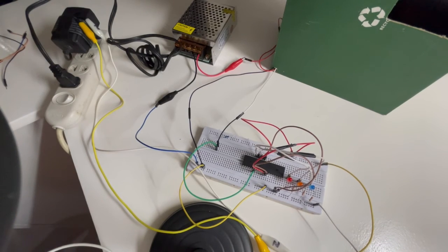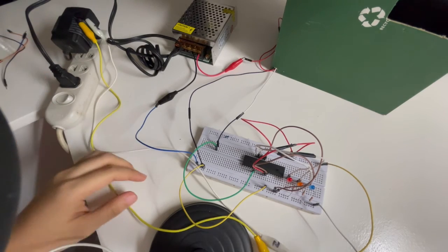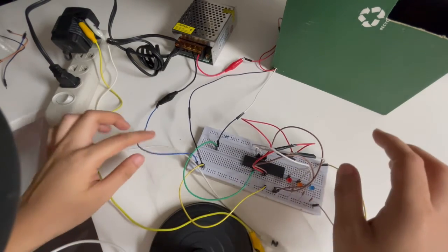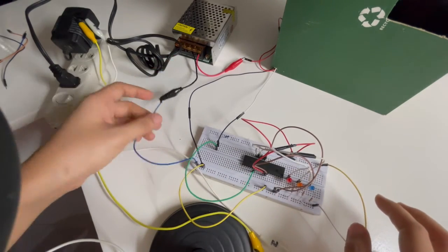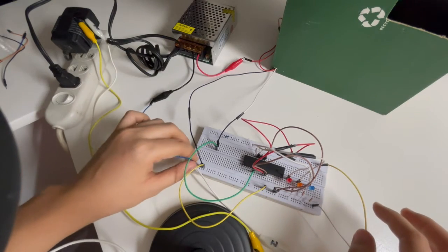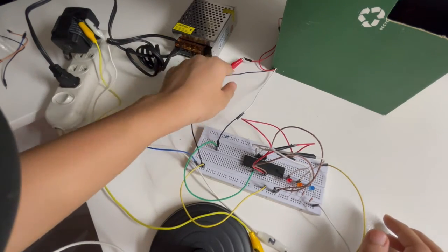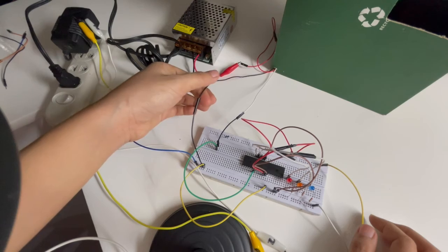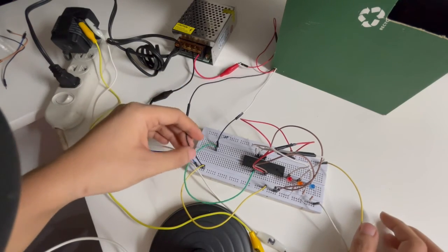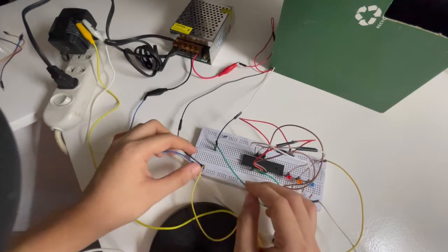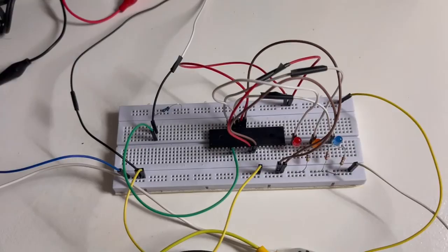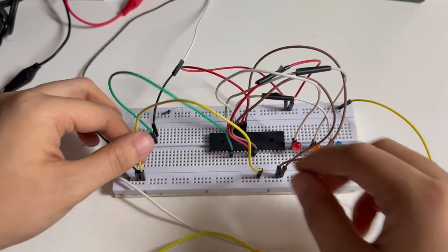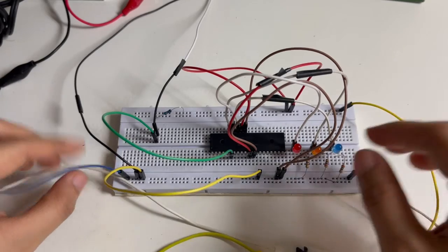For the connection of the circuit, this is the 5-volt power supply. It is connected to the positive terminal and the negative terminal here. And also, for the 12-volt power supply, the negative is connected to the negative side, and the positive is connected to the coin acceptor itself, positive V. This black wire here is for the ground of the coin acceptor. It is grounded altogether here. Let me just zoom in there. And as you can see, I connected both grounds of the 5-volt connection and the 12-volt connection.